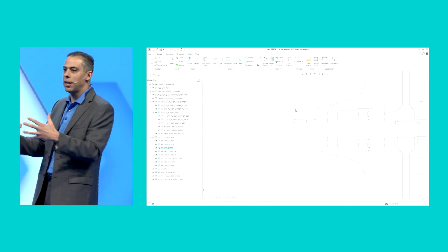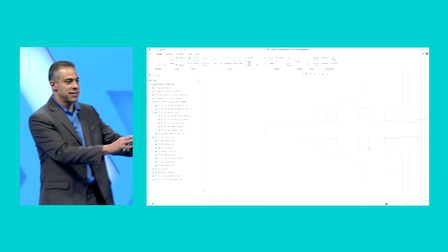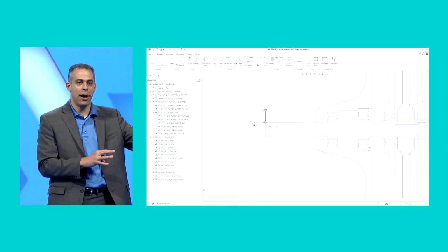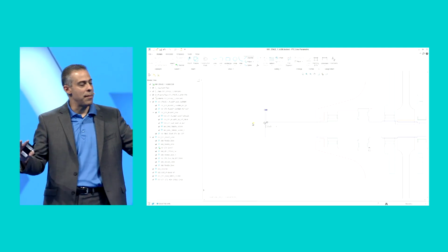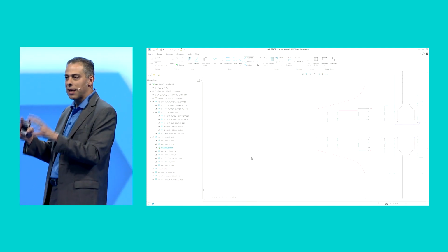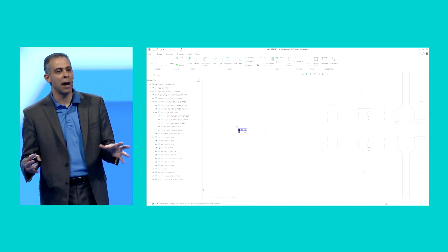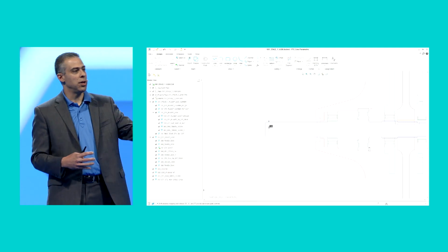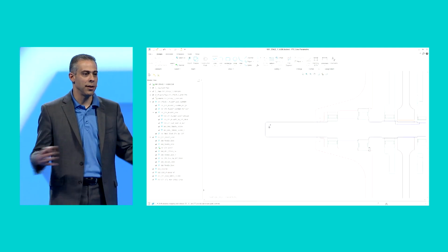And now the engineer whose assignment is to work on that sub-layout can work on it apart from the master layout. The engineer can work on that separately. It's the same type of collaborative environment you would imagine with someone in your design team working on a particular part that's part of an assembly. It works exactly the same way. I can go in and make changes to that sub-layout like you see in here. I extended the shaft. I added a keyway. This is important for the interface. And now when I'm done, I incorporate that back into the master layout.